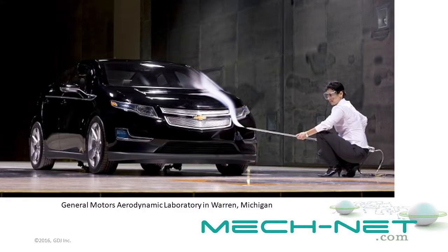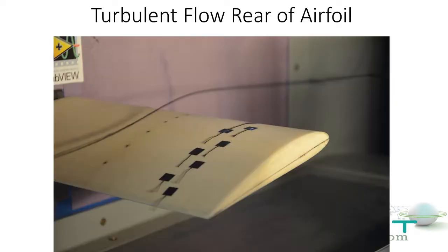Here is a technician using smoke to test the airflow over an automobile in the General Motors Aerodynamic Laboratory in Warren, Michigan. Here is an example of a combination of long and short yarn tufts being used to illustrate the flow pattern over the upper surface of an airfoil. Note the tufts on the front of the airfoil are showing a laminar flow, while the tufts on the rear are showing a detached, turbulent flow.